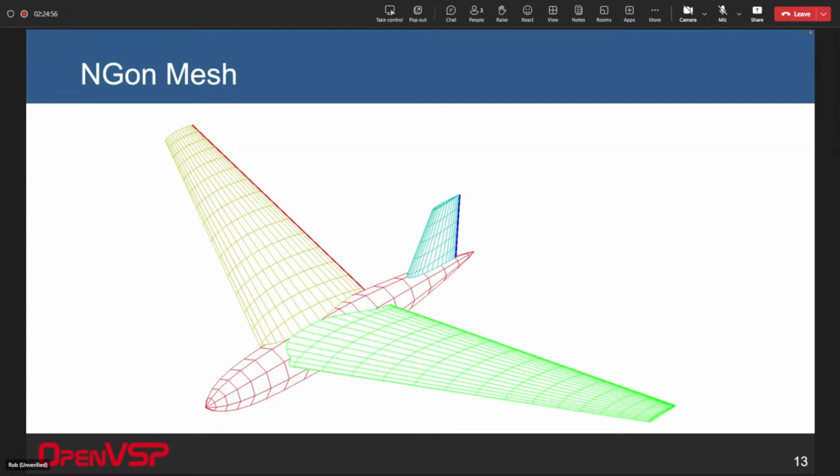And so what I can do is after we do that CompGeom and we have all the triangles, I can go back and remove diagonals to reconstruct triangles into quads, but actually here at the intersection, I'm reconstructing it into a polygon of an arbitrary number of sides. Just quickly looking at it, this polygon right here is going to have at least 1, 2, 3, 4, 5, 6, 7. It's going to have at least 7 edges.